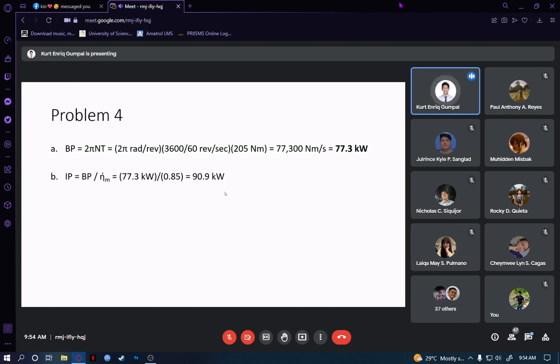Okay? We can derive that, right? Since BP over IP is equal to efficiency, you have your BP, you have your efficiency, so you can get your IP immediately. So it's 90.9. Now, you have your brake mean effective pressure.